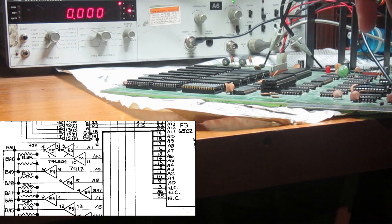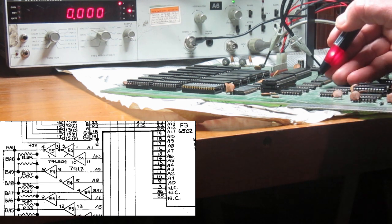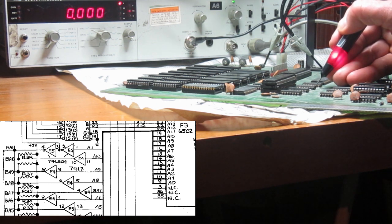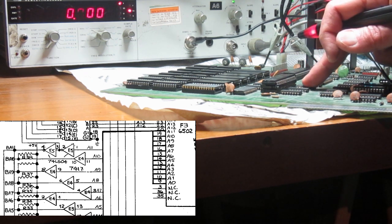For example, we have A9 entering pin 9 of E4. E4 is this one, pin 9 is this one. So the address is coming to the input of the buffer, then it exits from pin 8, which is this one. So it's toggling again. So this buffer is working.